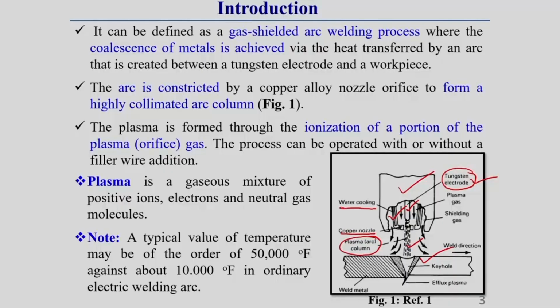That is why we generally get very high intensity heat due to this constriction of the arc, because here the arc's diameter is reduced by this water-cooled copper nozzle. You should keep this in mind.